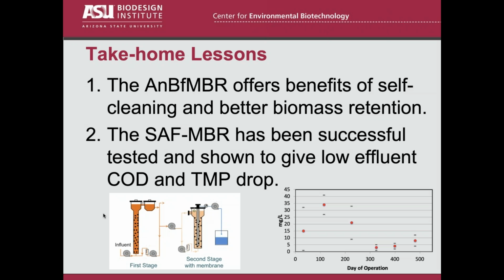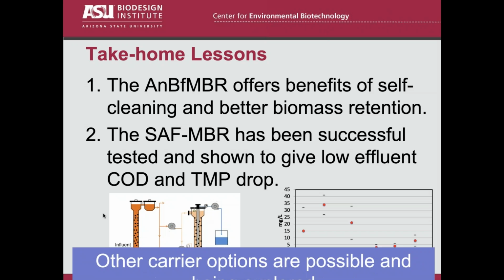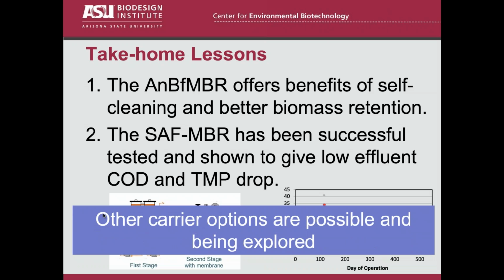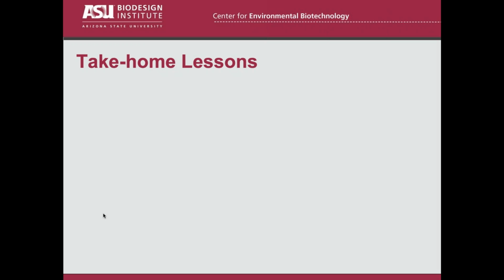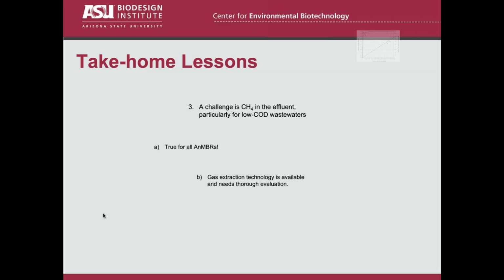It works. It gives really low effluent COD, low transmembrane pressure drop. It's really, really good. And we can try other carriers. You know, we don't have to be wedded to granular activated carbon. In fact, our group is beginning to test other carriers in this application. But it's not all roses yet.